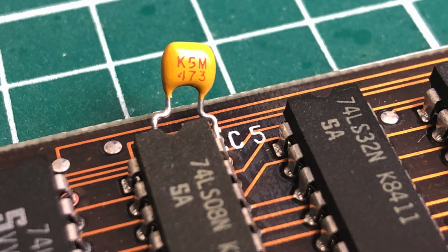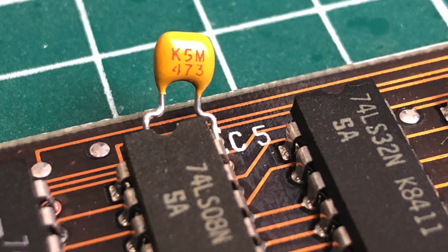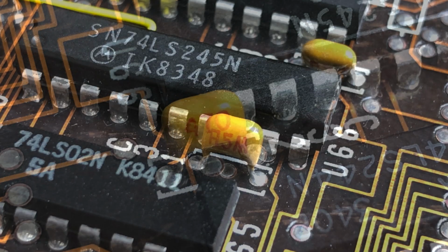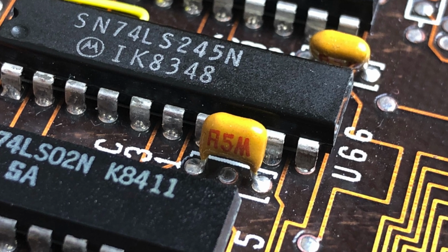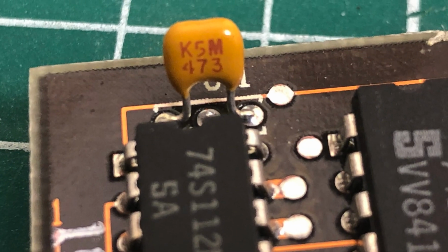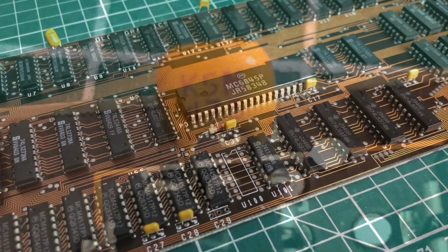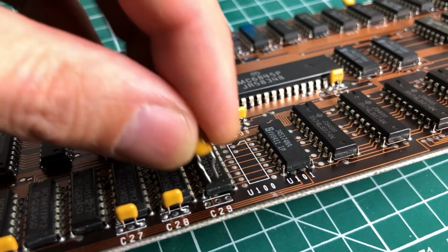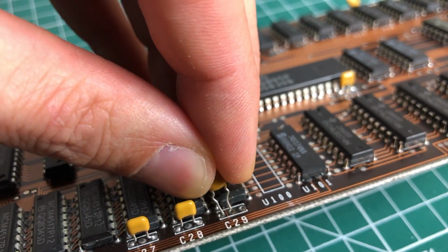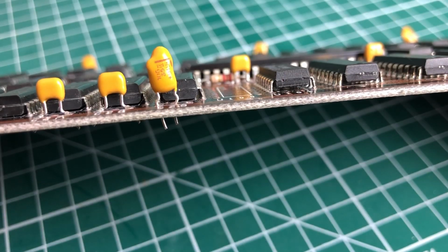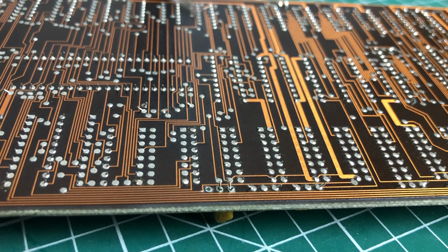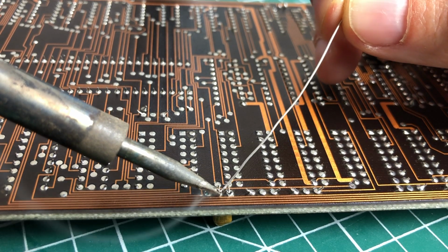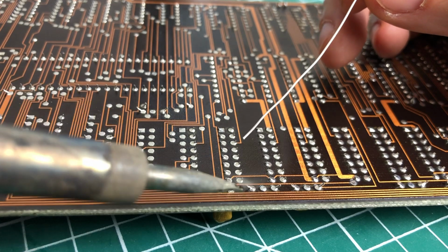There are obviously lots of capacitors on the CGA card. I checked pretty much all of them. I desoldered them. I checked them using an ESR meter, and I didn't find any issues with it. So it remains a mystery to me why the card is not working. There is one socketed chip on the card. I also replaced that one, but it just fails to start for some reason, making it very difficult. So up until now I have no idea why the card is not working.